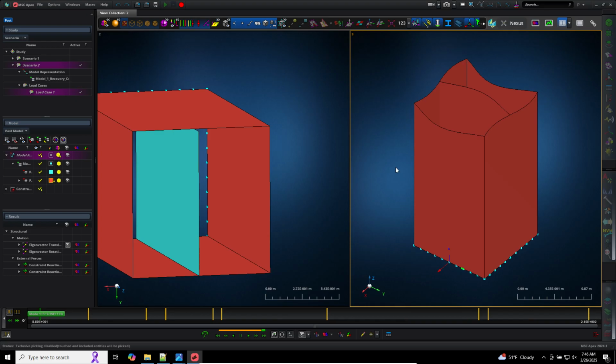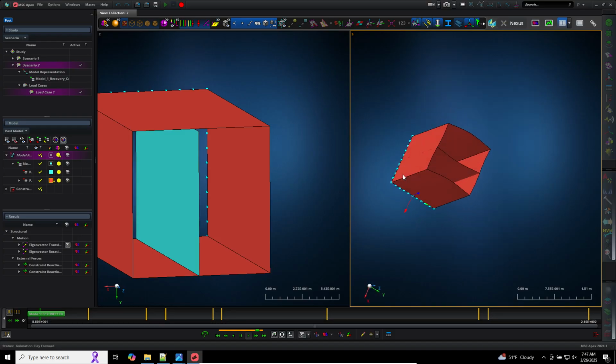We're going to animate modes 1 through 10 and just see what's going on. Here I've selected the window on the right. You can see that the border is orange or yellow, so I'm actively modifying animation settings for the right window. We'll click on play, and the speed of the animation is too fast, so at the bottom center, we'll move the slider a little to the left. This will calm the animation down a little. A moment ago I was a little excited.